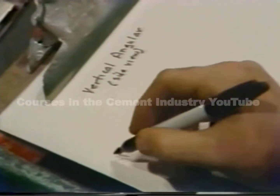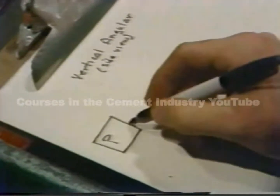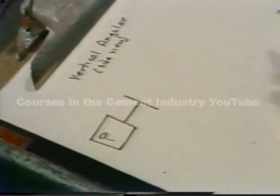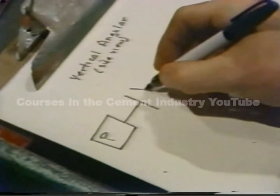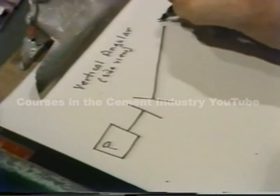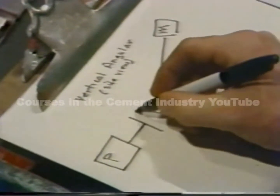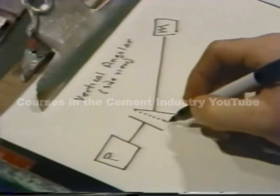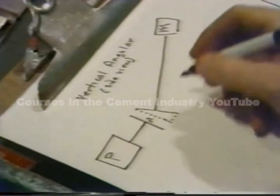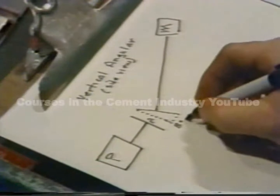The sketch shows the pump and the pump shaft. The pump will remain in position while the motor is moved in the alignment. The motor is drawn, showing an exaggeration of the angular misalignment discovered by the negative 0.008 of an inch reading on the dial when it was at the bottom. The dotted line labeled A shows where he wants the shaft to be. And B, of course, is the amount of misalignment already measured.